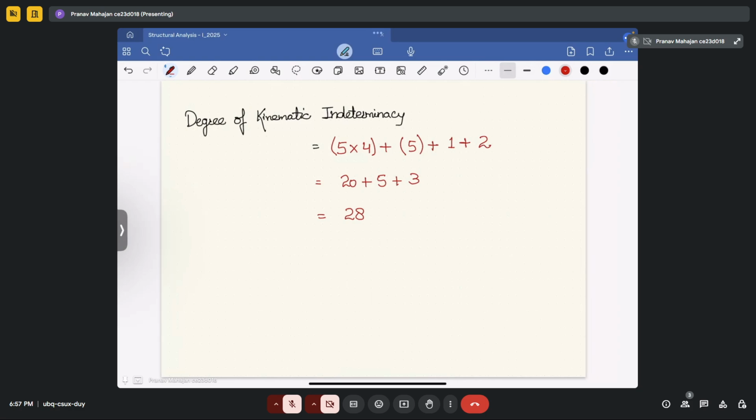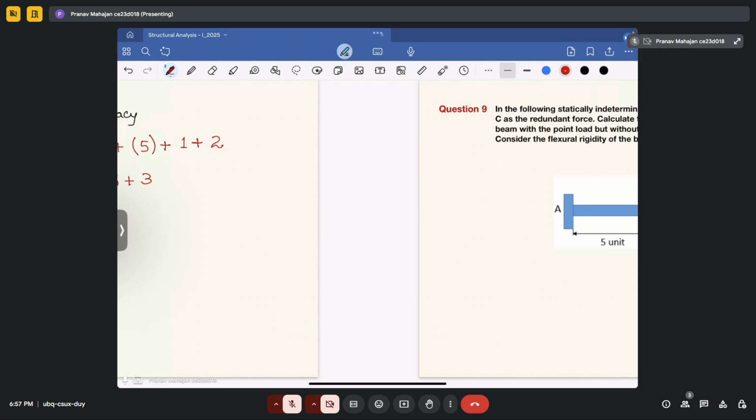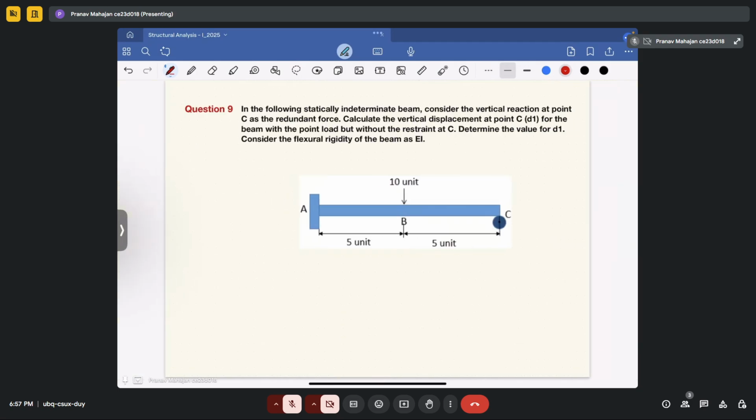Okay. So now your next question is, you are available with one propped cantilever. So that means if the cantilever beam is propped, this structure is indeterminate. Okay, now you know the structure is indeterminate. So depending upon the complexity of the problem, you can choose any of the methods. You can choose either the force method, or you can choose the stiffness method to solve the problem. So for the sake of understanding, we will start this session using force method.